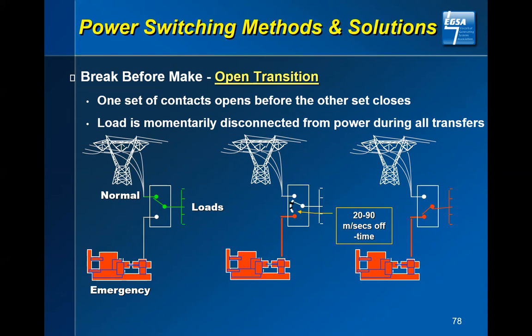At least in Texas, under the Public Utility Commission, the PUC rules, they have what is called momentary overlap. And you have to be on and off within 1 second. If you're on and off in more time than that, now you are under what is called extended parallel, and you may have a whole bunch more products such as selective relays, protective relays, and such that need to be on here. This switch, when operated properly, will make that transfer within 100 milliseconds